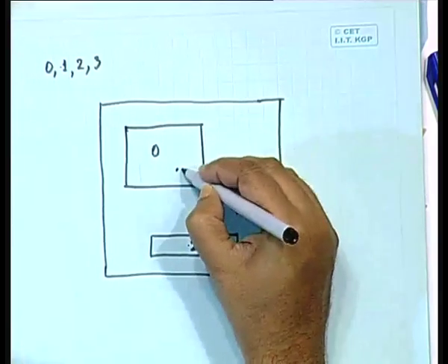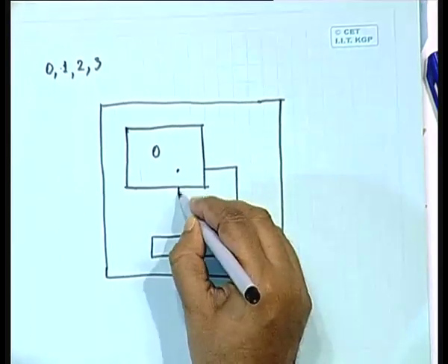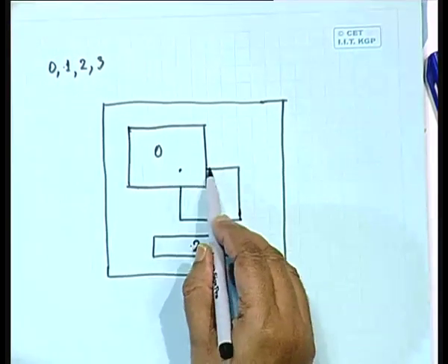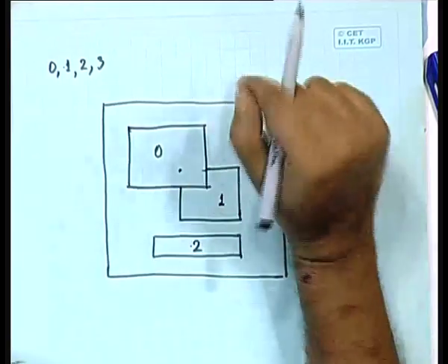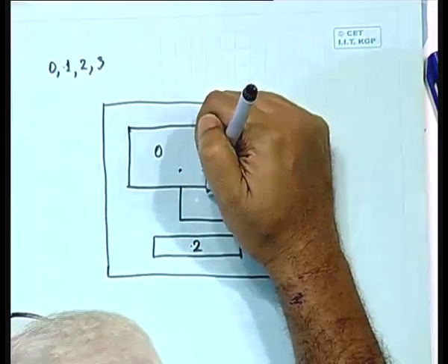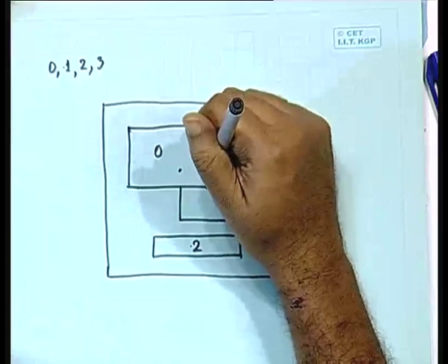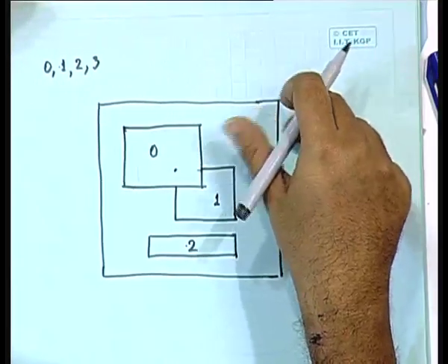Which means it is going to include all the macro blocks which fall within this boundary, but what about these ones? These ones also will come under group 1, but they are already defined as group 0 of the slices, and in fact the lower slice group number has the overriding precedence.